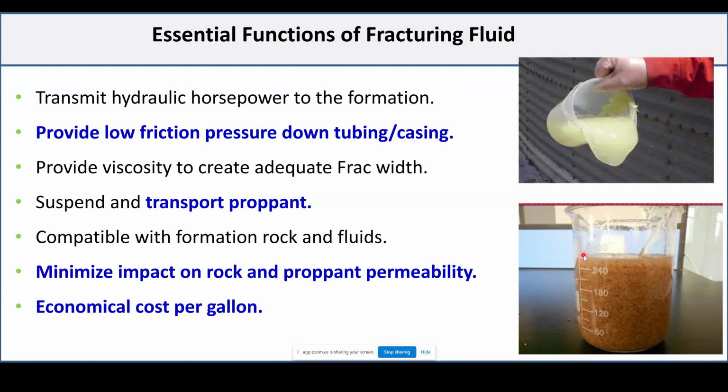What testing procedures are employed to ensure frac compatibility with the specific conditions? So testing, it depends. If we're talking about reservoir condition, you will have testing related to clay, which is usually the capillary suction test, roller oven test, and the proppant embedment. That is if you are evaluating the clay inhibitor. Based on these three tests, you can see if you are having minimum damage or not to your frac